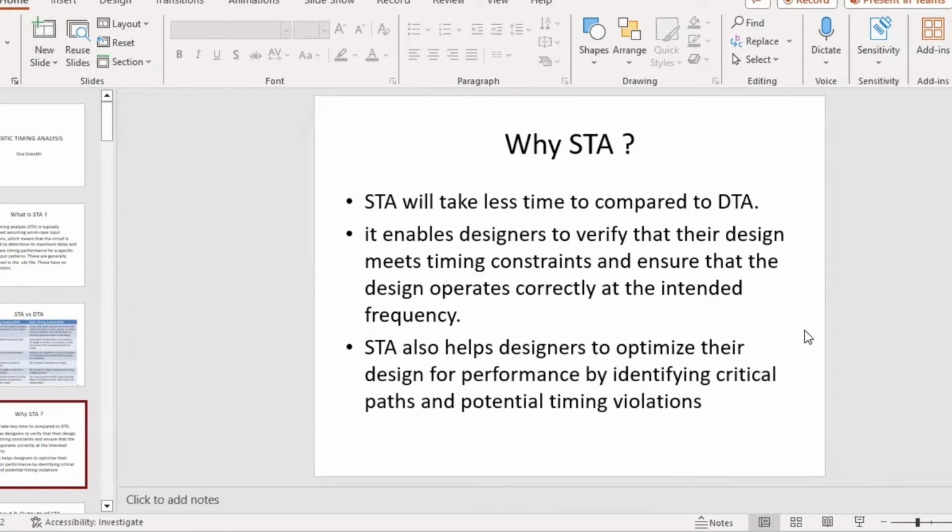One of the questions was what is setup time and hold time. So why are we getting both setup and hold violations in the same path? One of the root causes, I'm saying the answer, you can make note of it, is that constraints are not good. There may be chances that constraints are not good and a proper clock is not built.